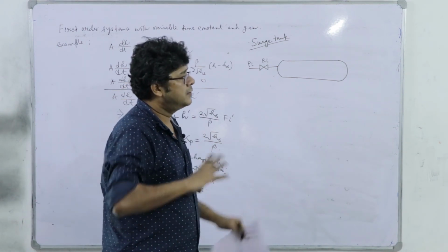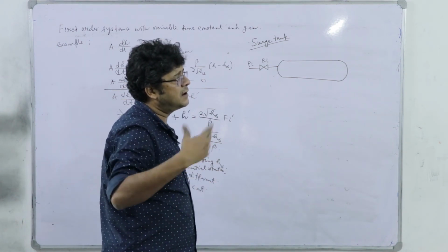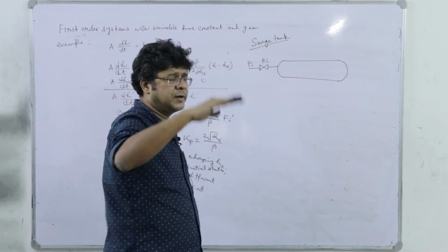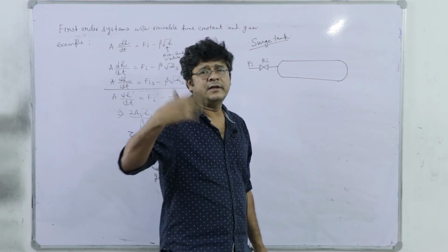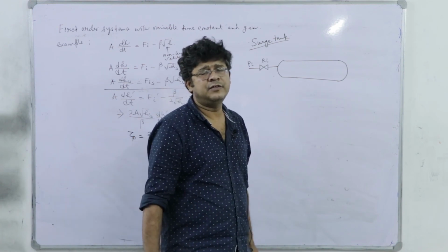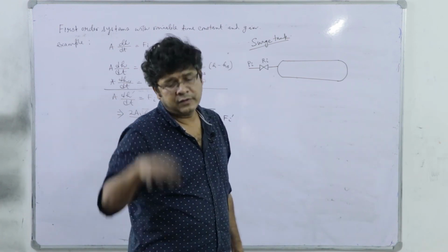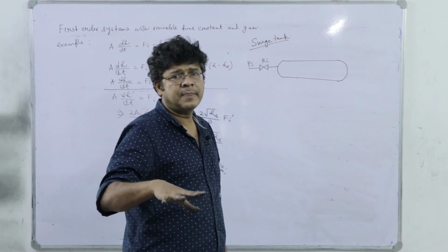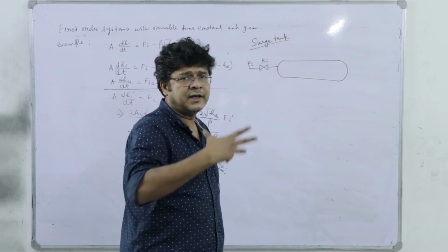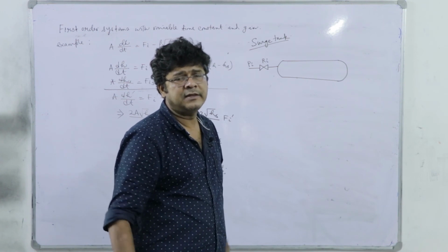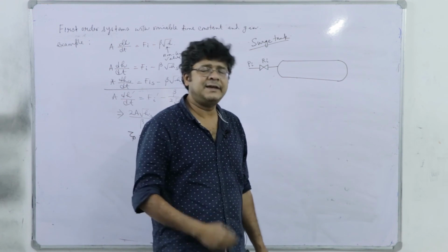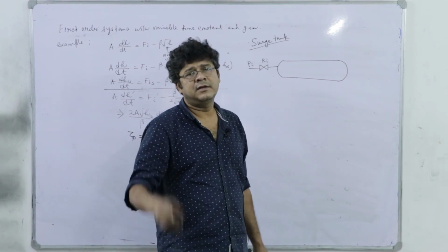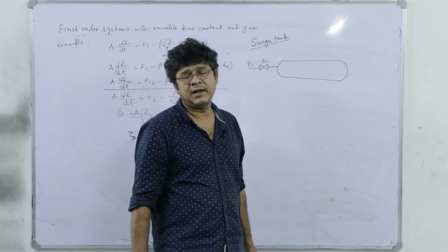So there is a control valve, and suddenly by mistake, or because of some safety issues in the downstream, you have closed the control valve. Once you close that valve, a back pressure develops upstream, which will propagate throughout the entire pipe network in the upstream section of that valve, right?